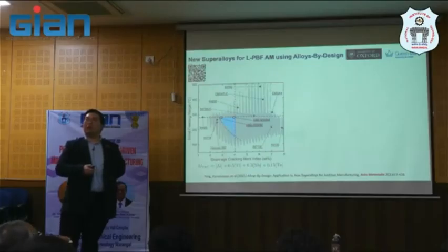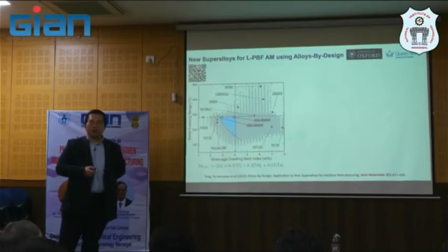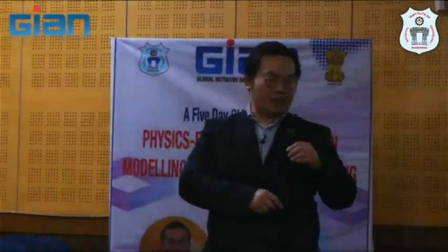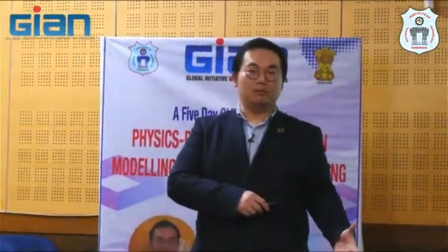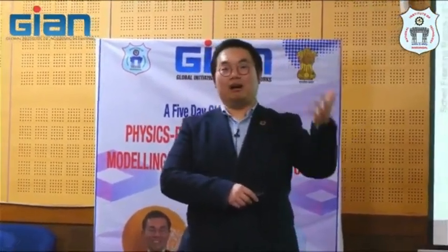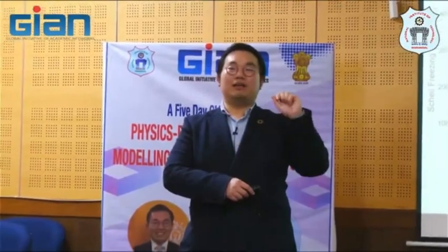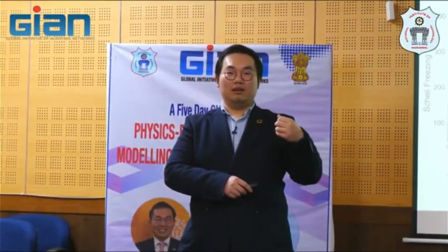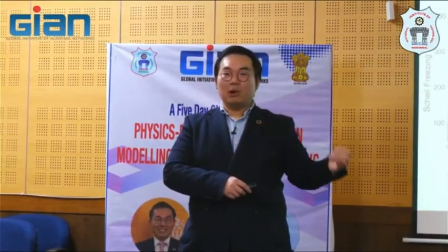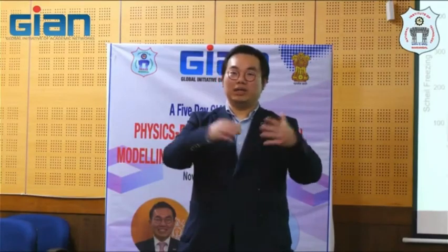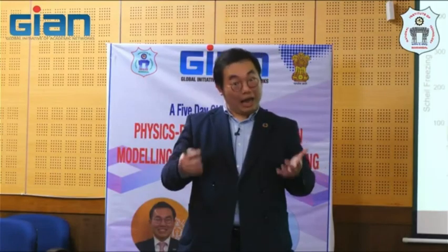I think there are so many things to do. It's not about heat treatment only. It's about the way you fabricate it as well. You cannot expect something highly segregated at the bottom and then homogenize it throughout, probably 30, 50 millimeters up. Later, in my opinion, you need to change your printing strategy, like scanning pattern, and try to control it in a different way to get a better thermal signal that can homogenize the structure as printed.